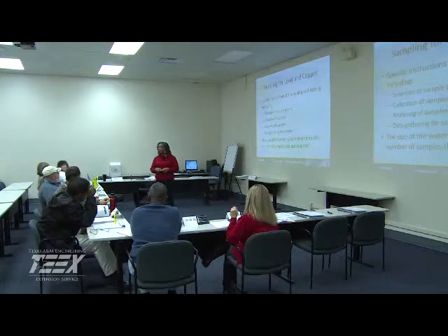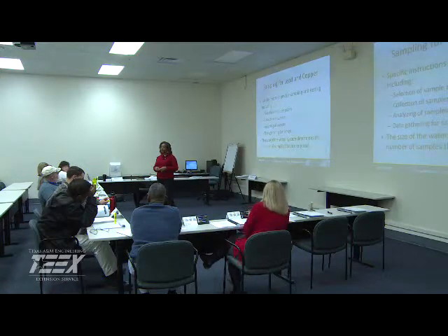On this section of sample points, they've got a mobile home park. What would make you go test someone's trailer that you know has copper pipes in it? Because when you get the letter, it tells everybody that they've got lead in their water. It's not specific, so everybody goes into a panic. So you know where those old trailers are that you really don't want to take a test with.